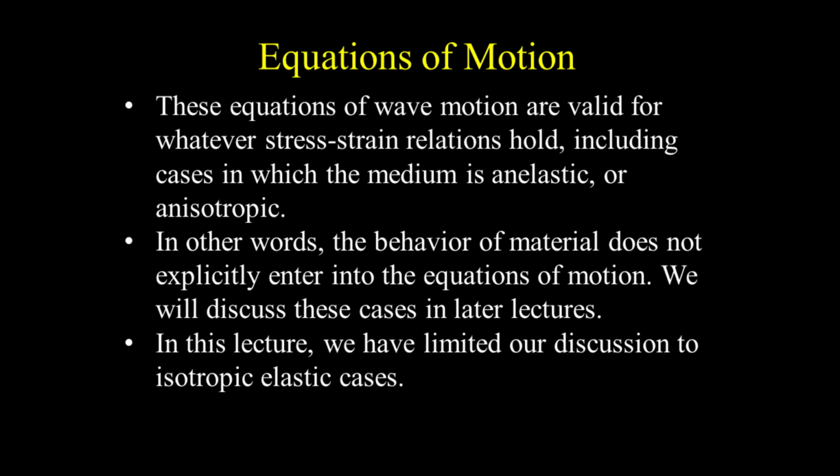These equations of wave motion are valid for whatever stress-strain relations hold, including cases in which the medium is inelastic or anisotropic. In other words, the behavior of material does not explicitly enter into the equations of motion. We will discuss these cases in future lectures. In this lecture, we have limited our discussion to isotropic elastic cases.